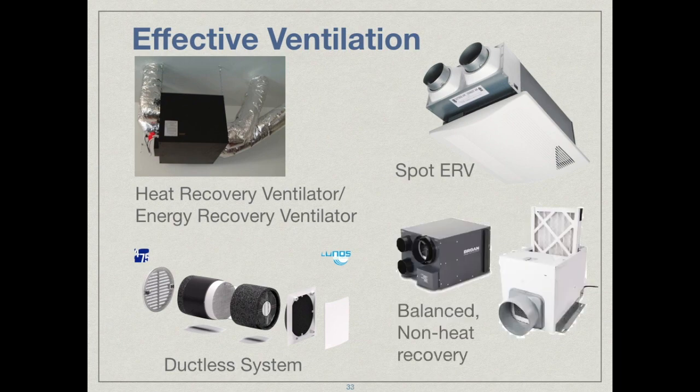I'd also like to propose something a little radical, and that is that we get rid of the heat recovery element and just stick with some really good balanced ventilation. If you have balanced ventilation, you can get fresh air in, you can take the stale air out, you could filter that incoming air, but if the heat recovery aspect is what's driving up the cost, then you can eliminate that cost by just not having heat recovery. And if you live in a fairly mild climate, I don't think that you're going to suffer too much in terms of the loss of that heat recovery in economic terms.